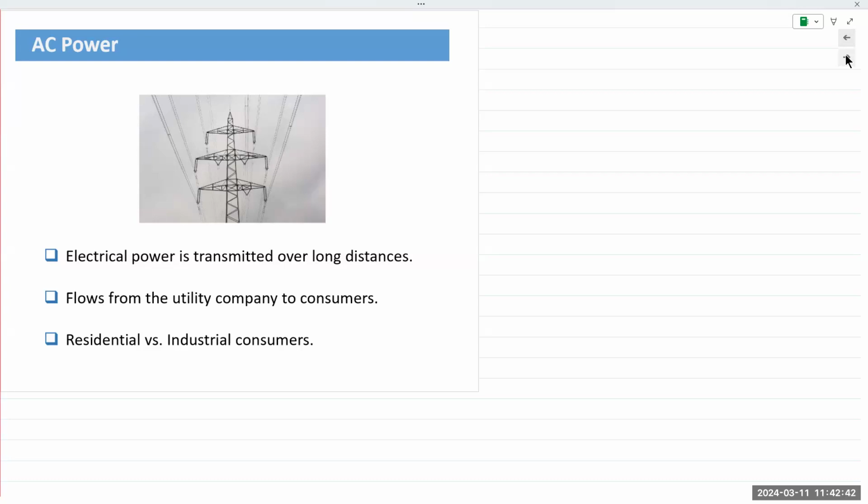L is the length of that piece of wire. So if you take a 100-foot length of extension cable or extension cord, it has some resistance, but that resistance value does not rise to the level of interference. You can plug a 100-foot long cable into an electrical power outlet, and at the end of that 100 feet, you would still expect 120 volts. It might have dropped to like 119 volts, perhaps, if it's not very well made. But that does not rise to the level of interference. That 120 volts is not going to drop to less than 100. Does that make sense? Right?